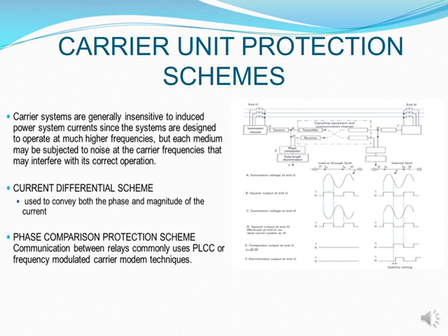Here again, you can have a current differential scheme, which is used to convey both the phase and magnitude of your current at either end, or you can have a phase comparison protection scheme, of which the communication between your relays commonly uses what we know as a PLCC or a frequency modulated carrier modem technique. The diagram on the right hand side shows how this scenario is put together.